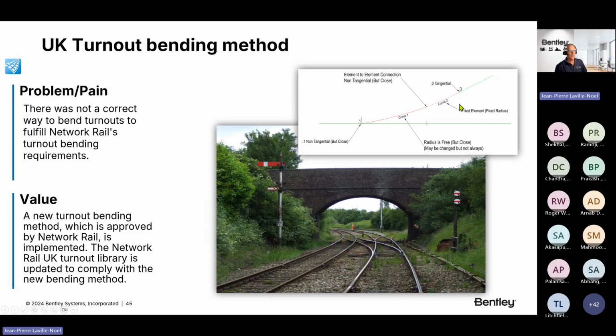So what we ensure is that the last point is good, the heel on the branch, and that the last curve is good as well. Of course, the point one must be good. And sometimes, because of bending, it must adjust whether it's the tangency here or the curve, the first curve. So they say we can accept some discrepancy here on curve one, as long as last curve on point three are good. On point one location, of course, is good. Point one, which is the point of switch.